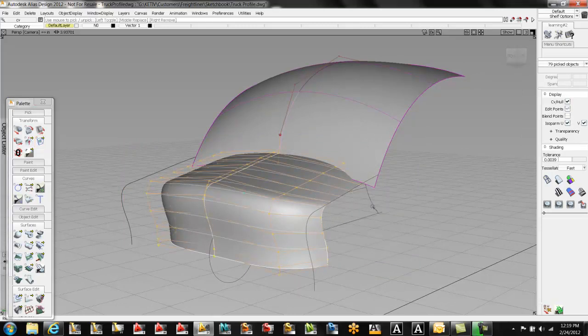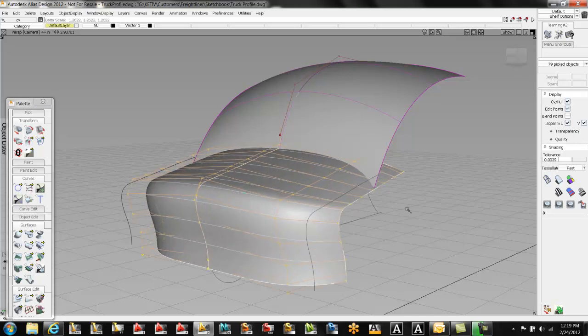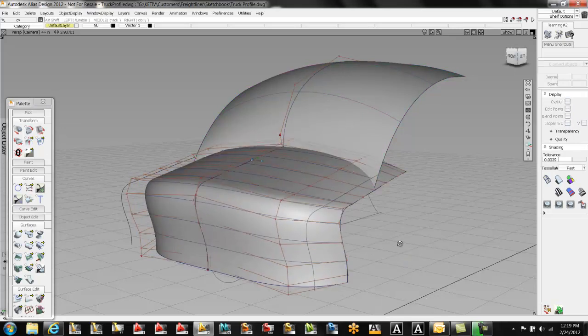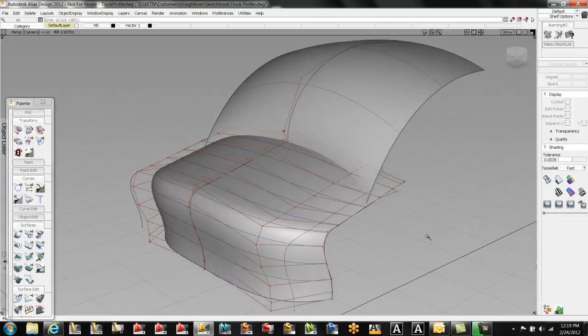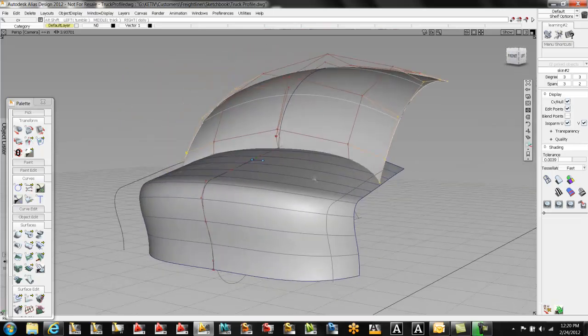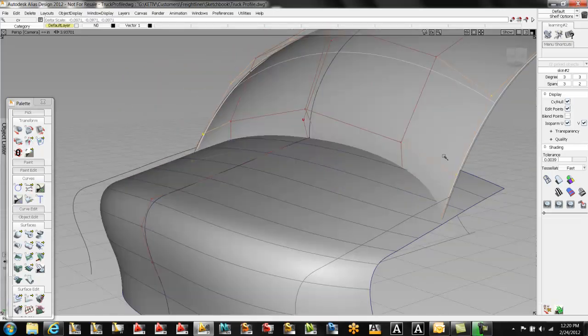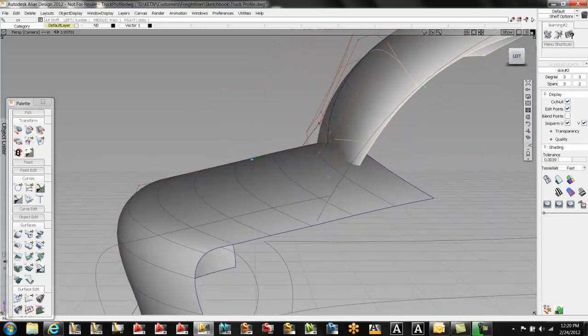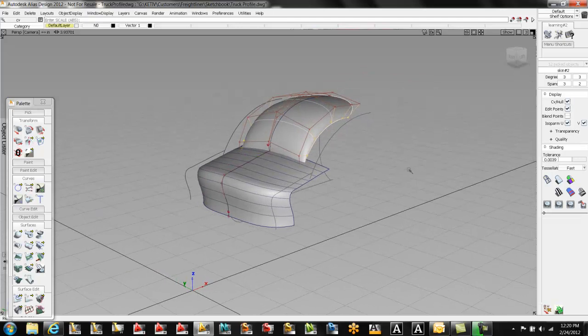Here I can just grab and I can scale my tools. Again, notice earlier you saw me manipulating the curves. Once I have a skin on there, I can grab that skin and start manipulating CVs on that skin. Adjust the scale a little bit, maybe sweep these back. Again, I'm just really quickly manipulating some of these surfaces I've created based off those initial curves and lines.